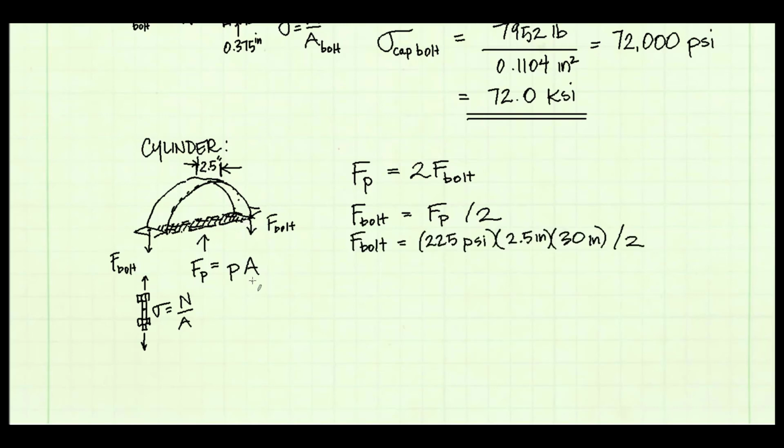Some people wonder why the area is not the curved area inside the tank. The reason is, my free body diagram cuts through the pressurized gas within the tank. So all forces are acting on the cut surface. That cut surface is through a pressurized gas, not around the inside radius of the tank. So the area the pressure is acting on is a rectangular area.